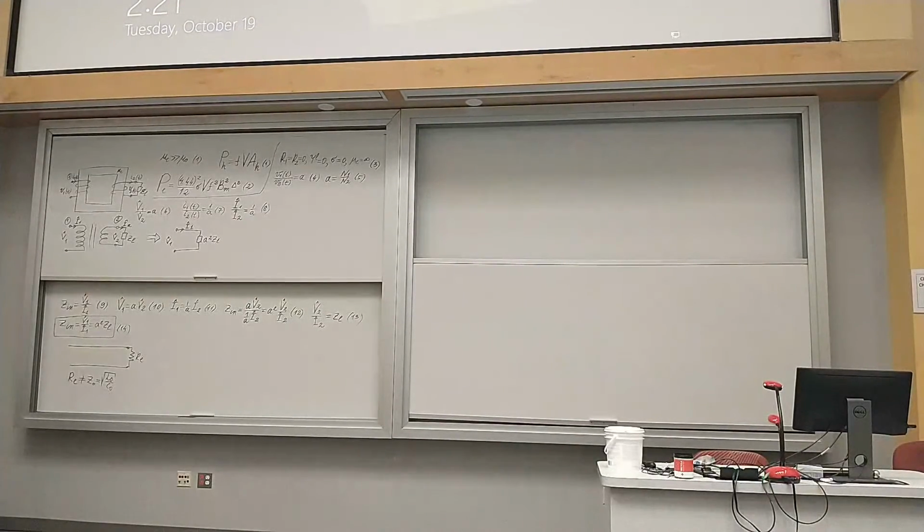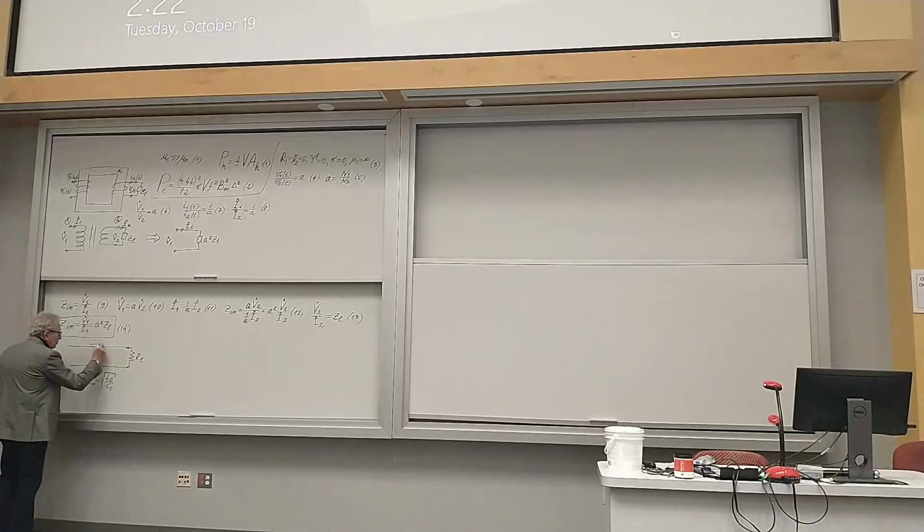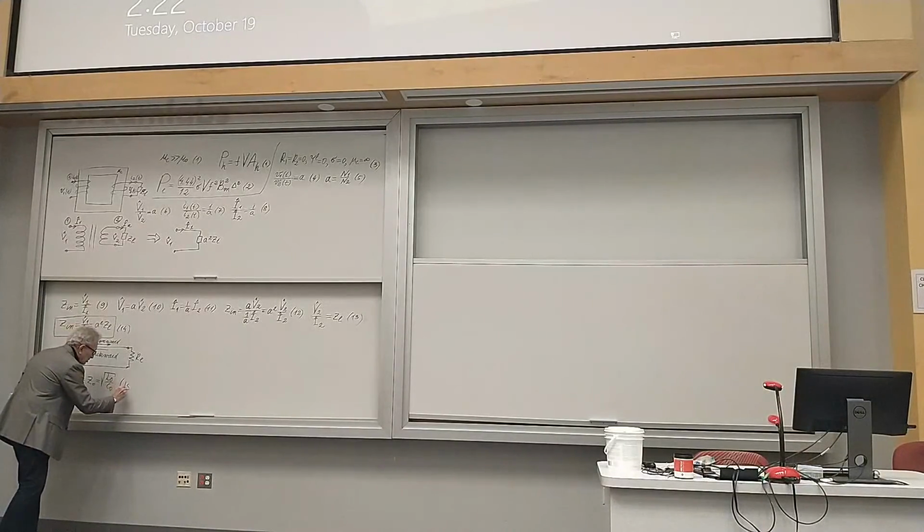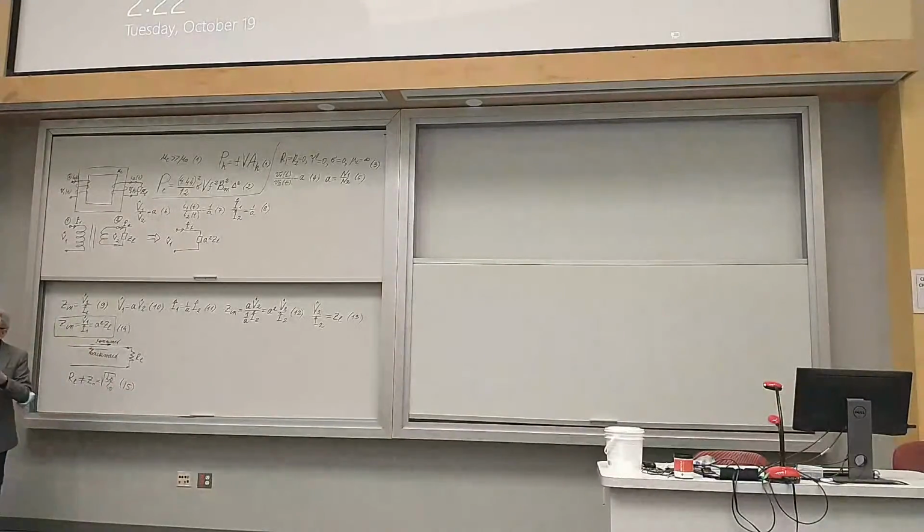And if it's not equal, there will be two waves here. One will be the forward wave, you studied this, and another will be the backward wave, moving in the opposite direction. But we are not interested in the backward wave. We want to transmit power, so there should be only a forward wave. How can we achieve this if we have this inequality? There is a way to achieve this by using transformers. That is why transformers are used for impedance matching purposes.